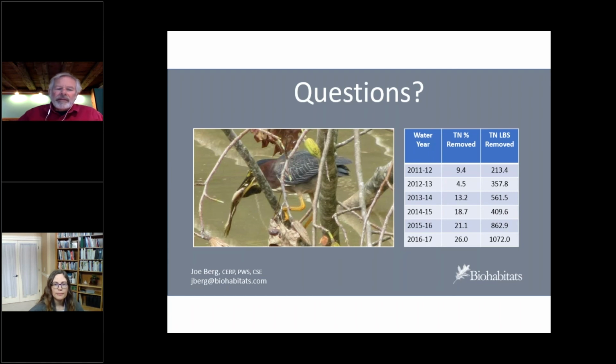Yeah. I mean, this approach has also been used in a design that we call regenerative stormwater conveyance. It's not a lateral treatment process like it is in a wetland, where you have a broad, shallow layer. You have this incised gully. You can backfill the gully with this sand and wood chip mix, and then create on top of that a series of riffles and pools, which receive stormwater, and it's sort of like a losing stream initially, and you're getting the same kind of hyporheic processing.